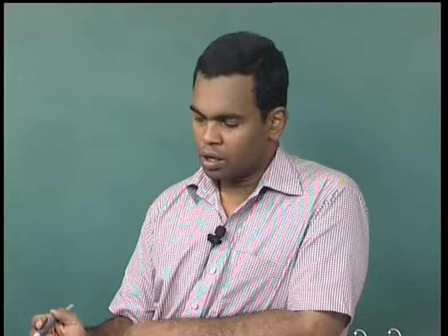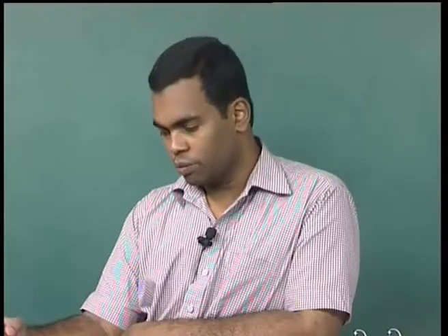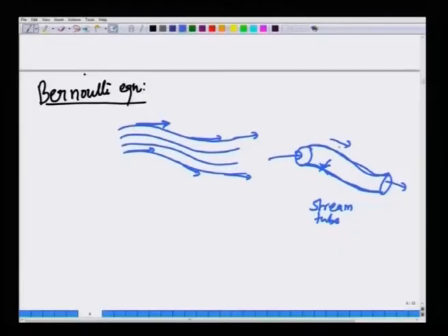But this is not like a rigid container, a rigid conduit, because the stream tube is surrounded by fluid and in general the fluid can exert stresses, viscous shear stresses. So, I want to apply the energy balance to this control volume, where you have a stream tube. The stream tube is our control volume.